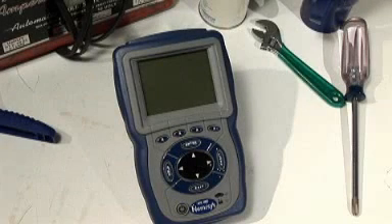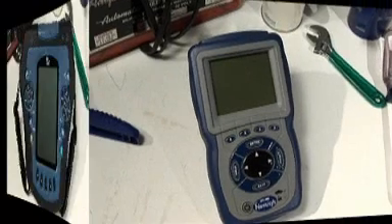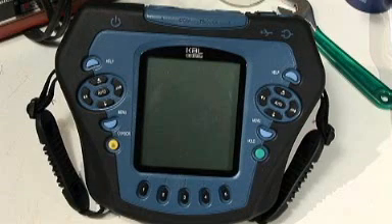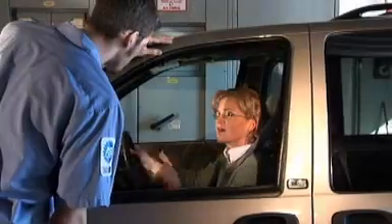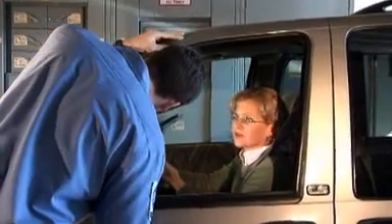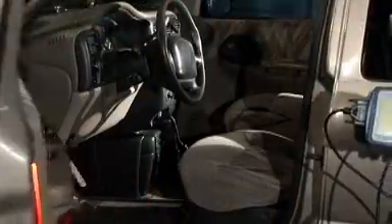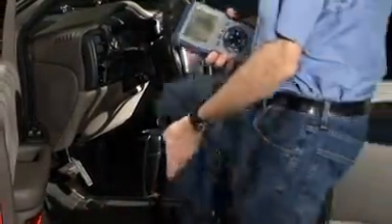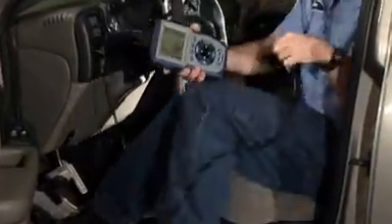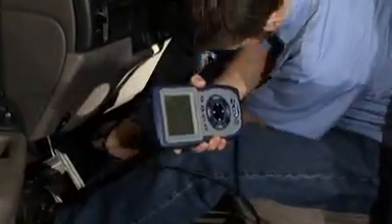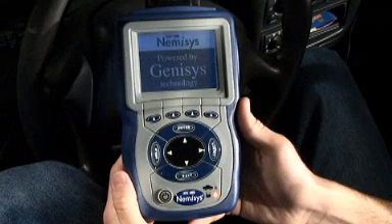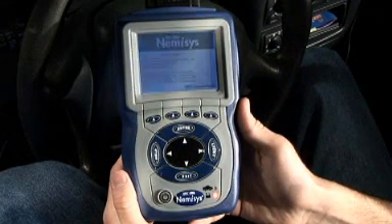We would now like to turn our attention to the mid-level professional tools that OTC offers for vehicle diagnostics. Same warning light scenario. Customer brings in a vehicle with a light on, only this time the technician uses a Nemesis to check the service engine soon light through the car's onboard computer. The Nemesis offers in-depth diagnostic coverage for a moderate price. He connects it to the car's computer and enters all the information on make, model, and year.